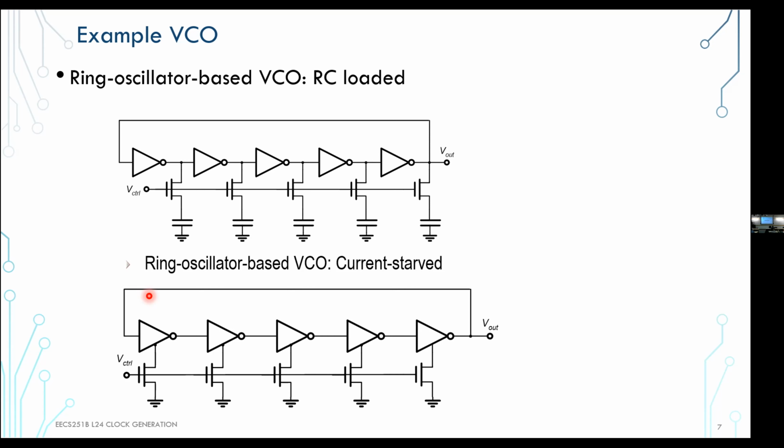If I apply a small noise here, it's actually not going to affect my timing at all, right? Only around the edge is any noise going to add to timing. So if you sweep this across, you're going to get some response. You do a derivative of that, and that will be, for this timing point, your impulse response. Then as you sweep this across, you're going to get the overall impulse response of the noise impacting the system. That's called the impulse sensitivity function.